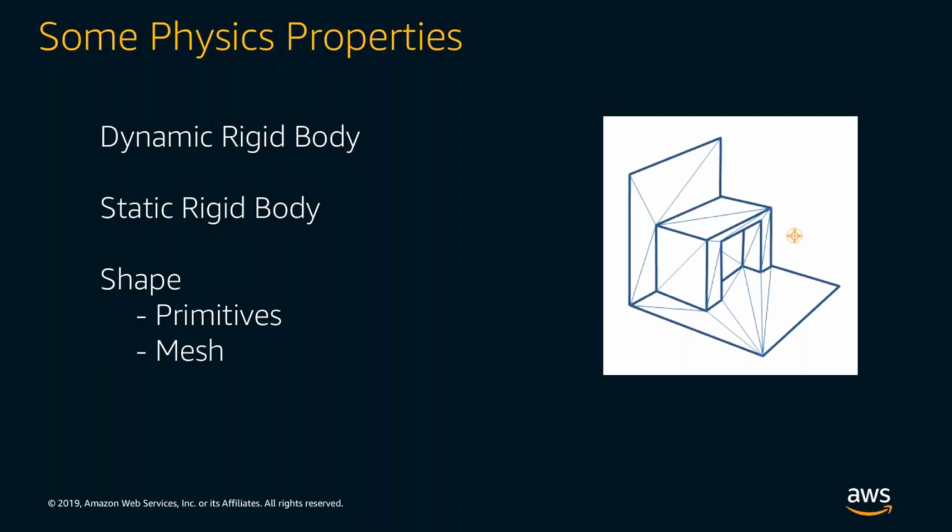They both take the actual mesh data, including, for example, vertices and indices info, passed in. However, convex mesh will typically involve a transformation process to generate a new convex hull, while triangle mesh is a collision triangle mesh, consisting of a collection of vertices and triangle indices, just like the original triangle mesh. And please note, there are some limitations for body shape combinations. For example, triangle mesh can only be used within a static body or kinematic dynamic body, as can plane and height field. So be careful when you try to use them the way you want.